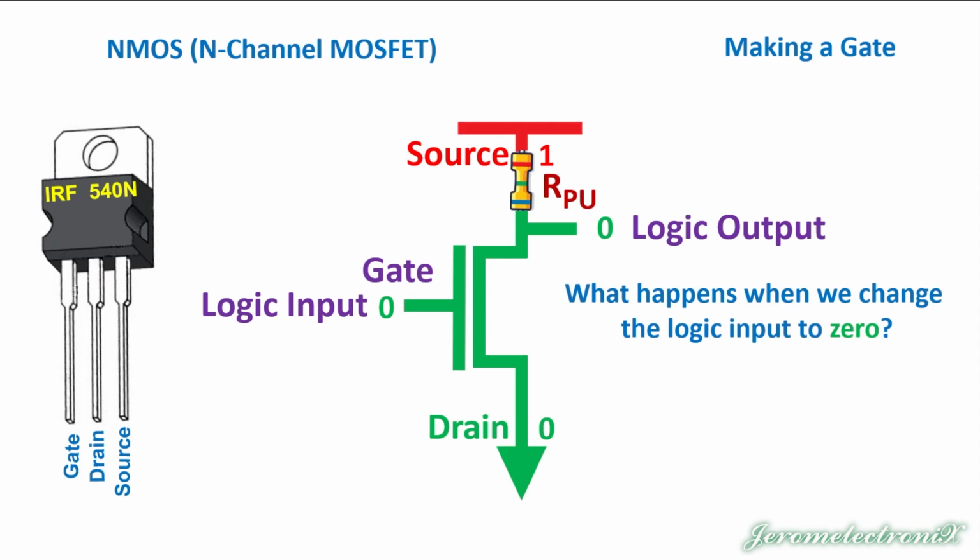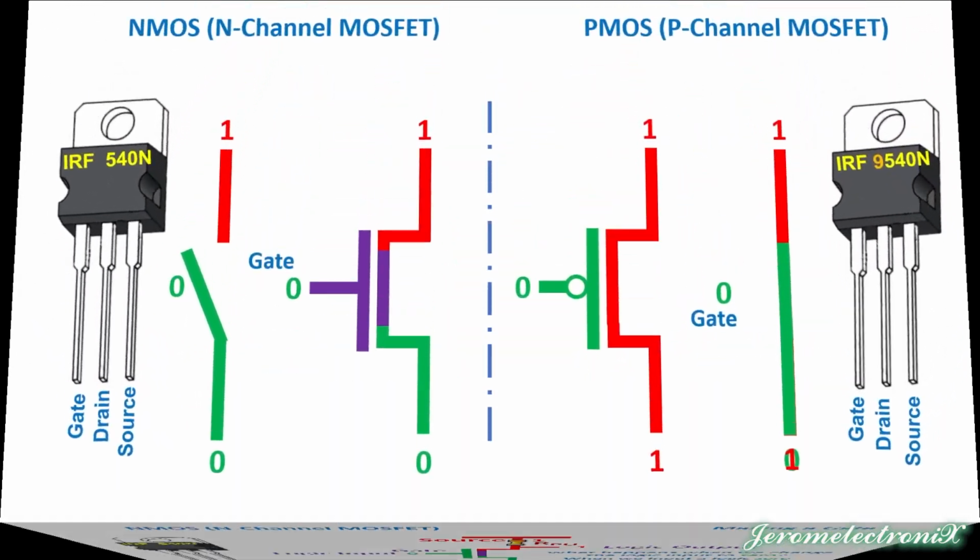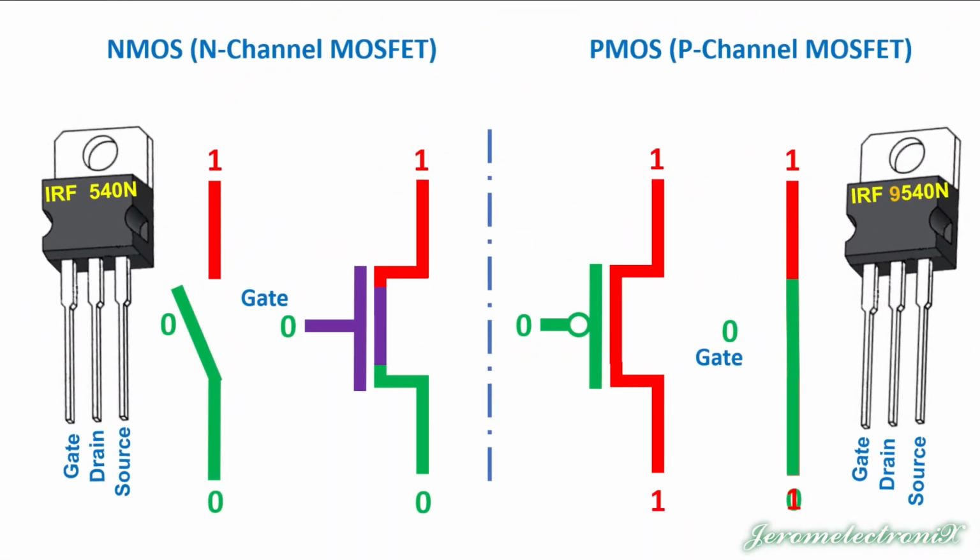That prevents flow across the bridge connecting the source and the drain, and that means the source above becomes 5 volts again, and that means we put a logic 0 in and a logic 1 came out, and that is exactly what we want our NOT gate inverter to do. So this actually works.